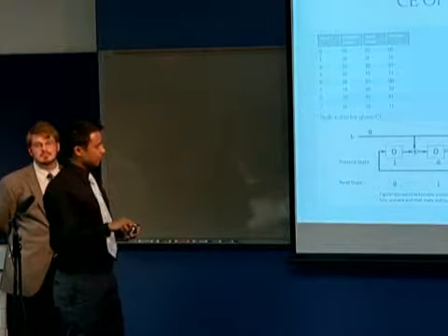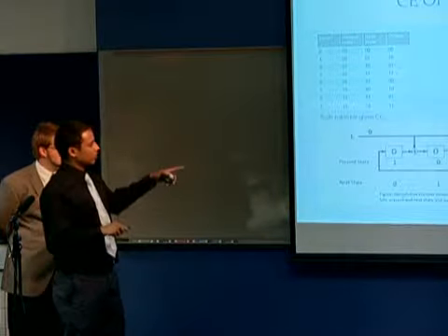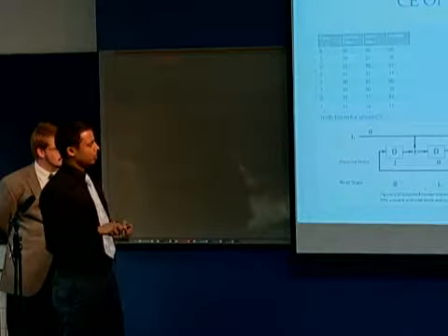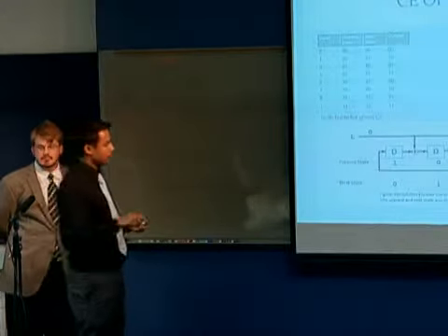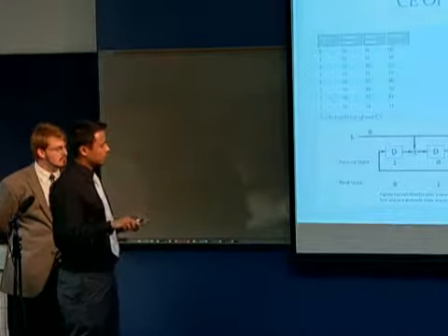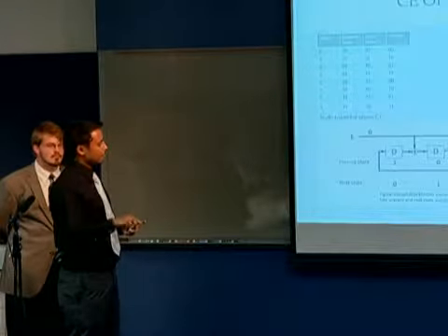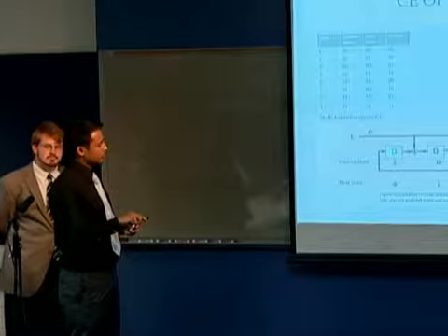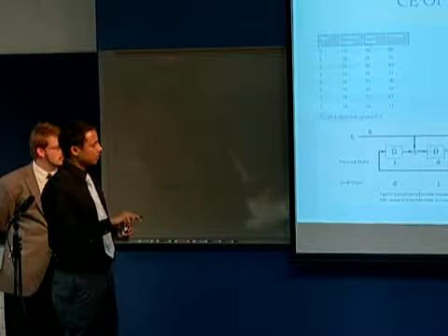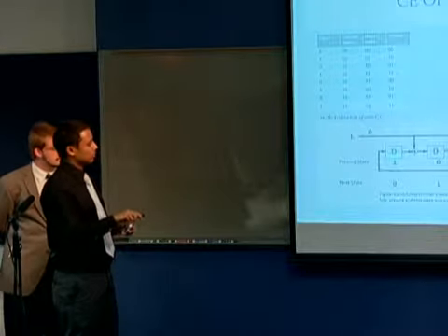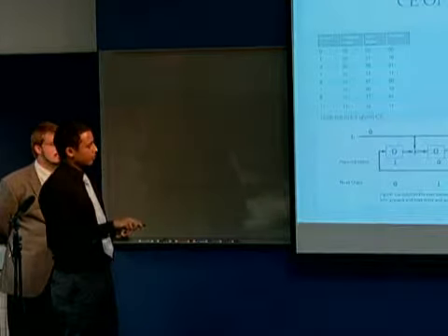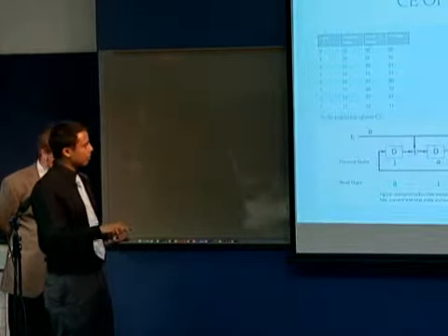So 0, 0 is W1. When it is in state 2 and the input is 0, the output from the convolution encoder would be W1. The next state is determined by this feedback loop. This 0 feeds back to this flip-flop, so that is 0. And then the previous 1 in here is XORed with a 0 to produce 1, so the next state is 0, 1.